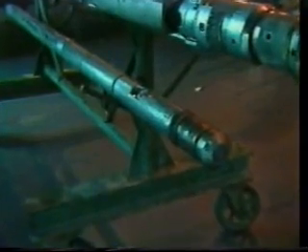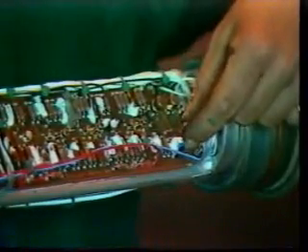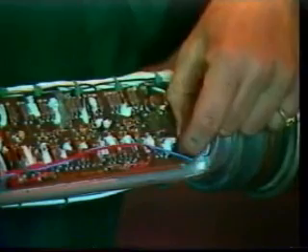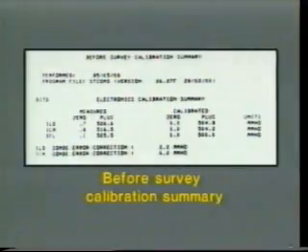For example, nuclear devices like this neutron density tool are tested with and without the calibration jigs designed to produce a predetermined tool response. Still other devices use built-in calibration tests, like the internal resistors in this resistivity tool. All before-survey calibration check data are added to the permanent records of each individual logging device and are included in the final printout of the logging survey.